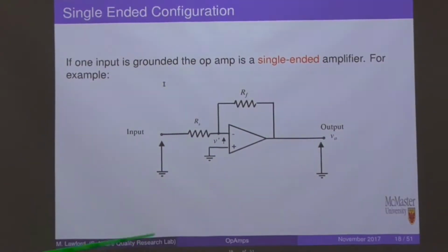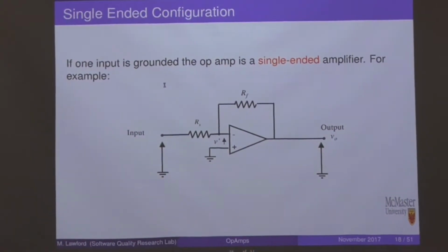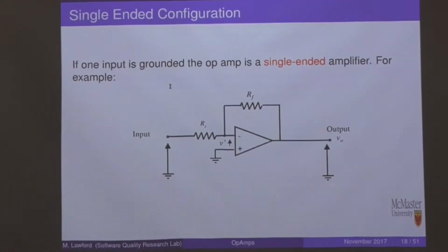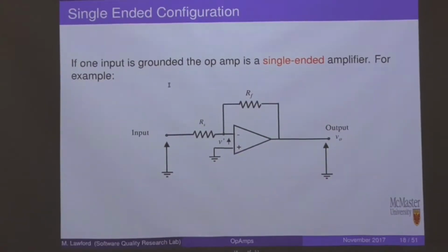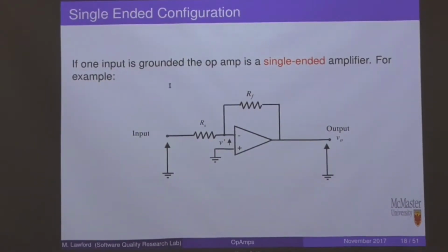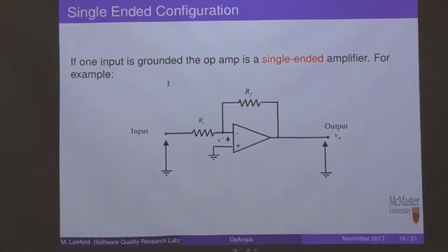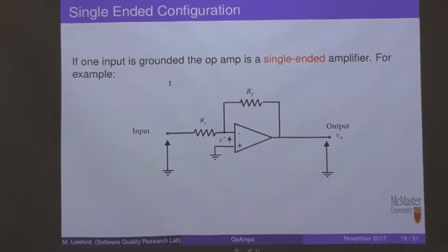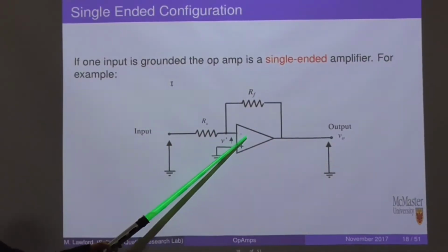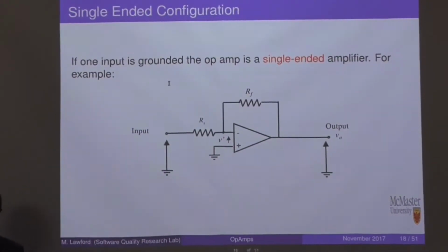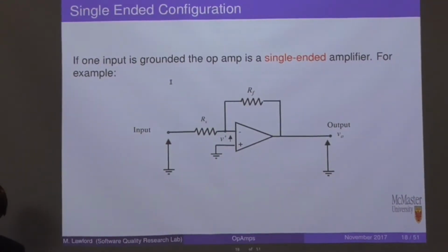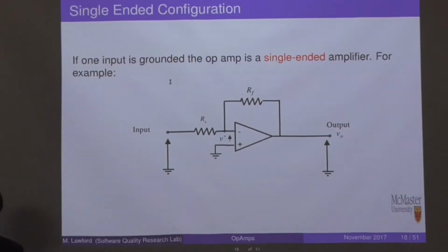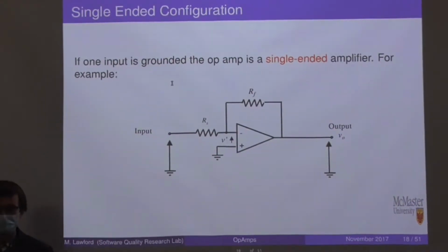Operational amplifiers' whole purpose is conditioning signals. So if you're allowing other signals in to interfere with how your op-amp is amplifying things, then you could be amplifying, for example, the 60 hertz oscillation that comes native with any household electricity service, right?